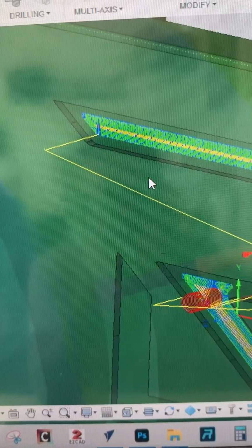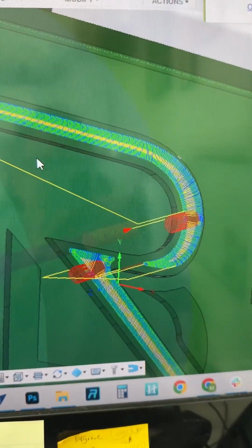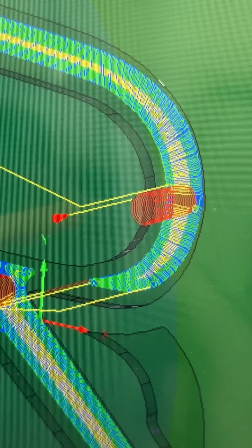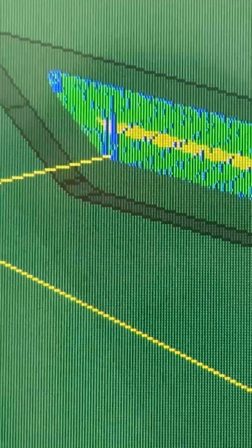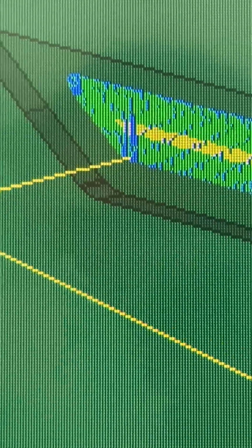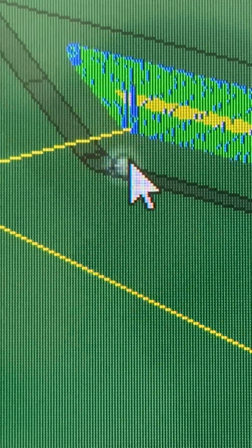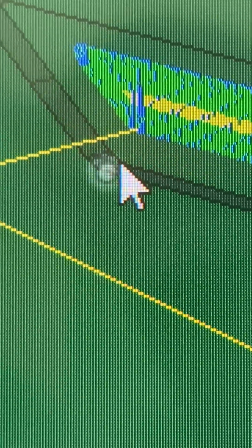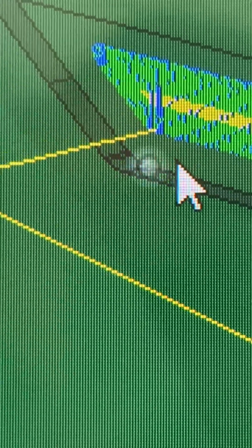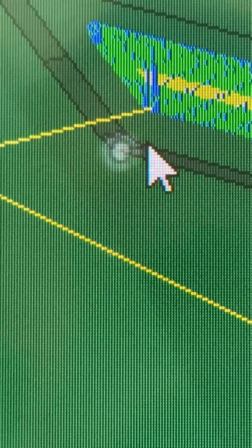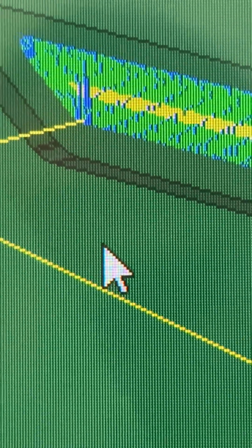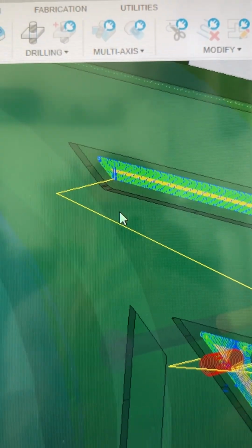an item. All right, so here's the CAD operation where in this area here, we're gonna ramp down with the 1/16 inch end mill. And then as we get into this area over here, which you can see, that's where the end mill, right in here, is gonna roll around this area here nicely, won't break because it's not a sharp corner. It'll get all of this because it's not a sharp corner, and it's gonna work, right? So no issues right there. Our end mill will fit in that area because I made that adjustment.